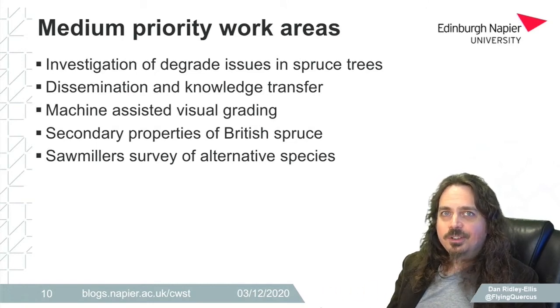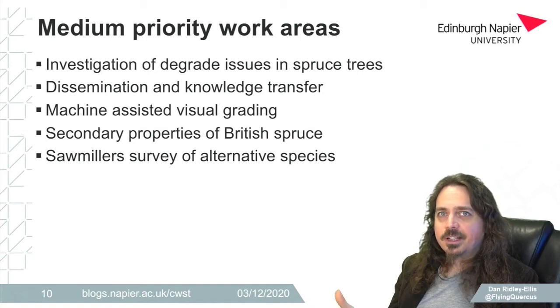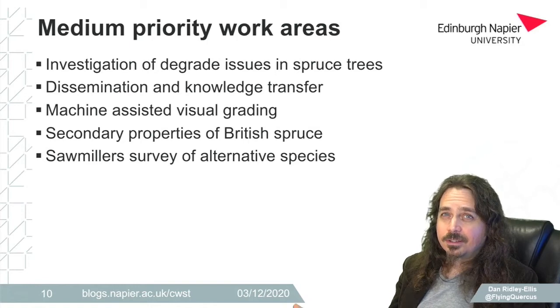We still need to look more at the secondary properties of British spruce, because that's another area where we can actually improve the designs, because often the designs are not governed by the strength and stiffness. Actually, they're governed by the secondary design properties, and we think there's potential to improve the values that are used in the declaration of performance to make the timber perform better in the structural calculations.